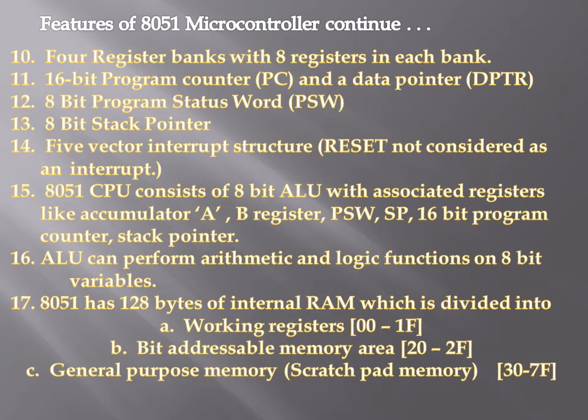Seeing the additional features, we have 4 register banks of 8 registers each, that makes it 32 registers. We have the 16-bit program counter and a data pointer, DPTR.